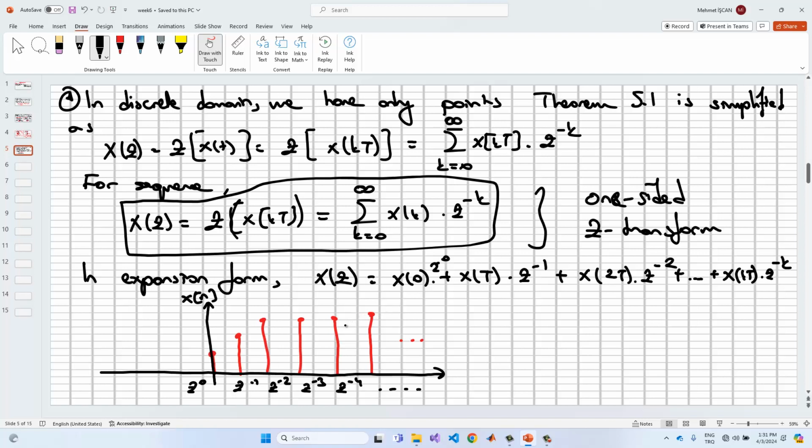Okay, and so if we have the Z transform in here, just like this one, and if dt is constant, then we can derive the transfer function or the pulse function to represent the dynamics of these values, because we assign the time variable or the sequence variable at the exponent parts in here.